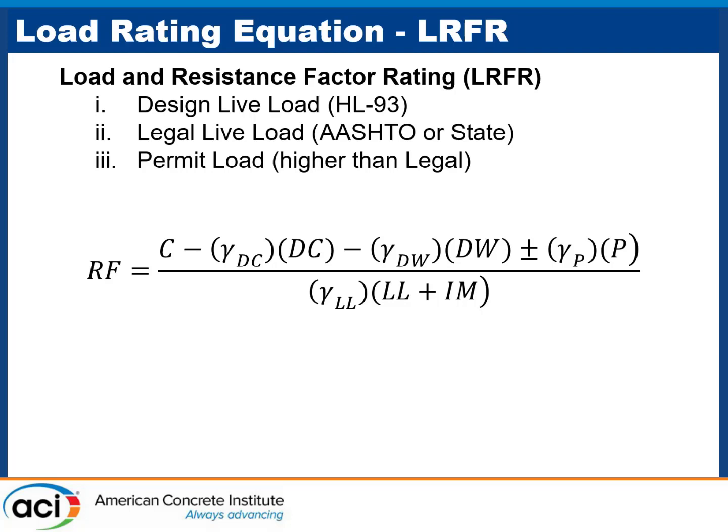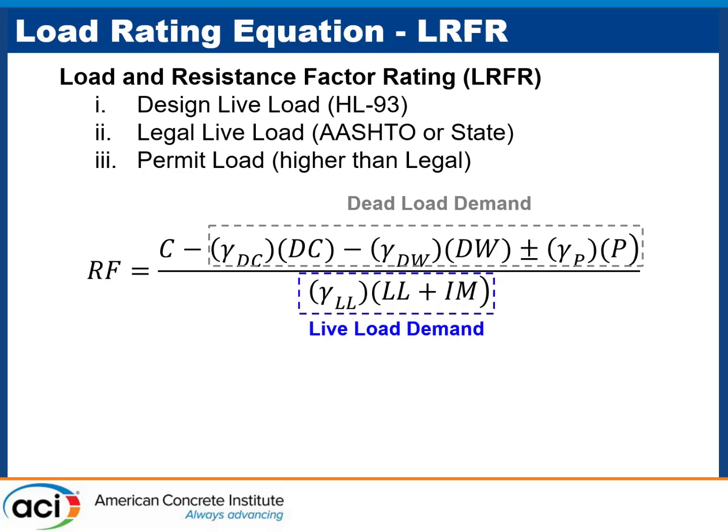how you want to include different types of damage in load rating. Let's focus on only AASHTO LRFR, and this is the equation for it. The load rating equation for AASHTO, this version, has three main components. Dead load, we are not touching it, it is what it is. The capacity and live load component. Live load is in the denominator, and the capacity is up top.